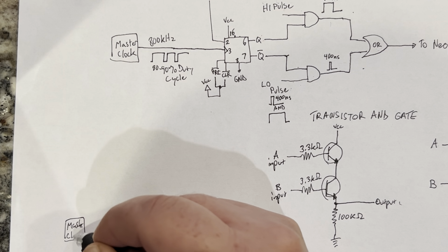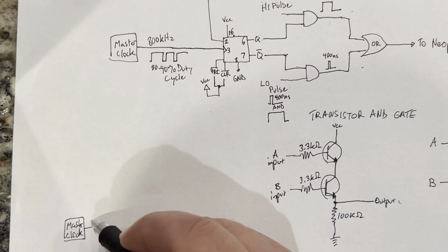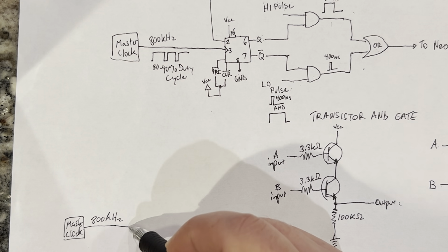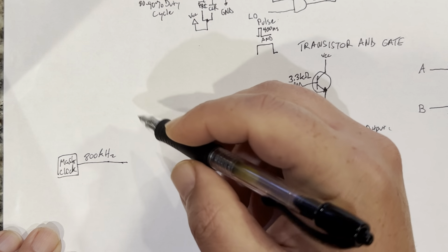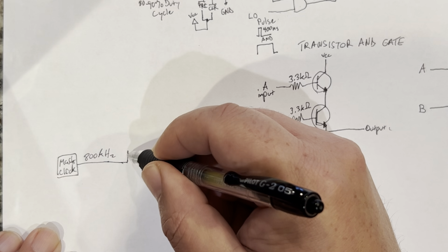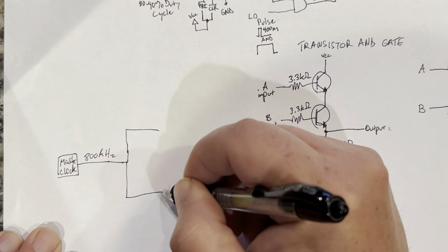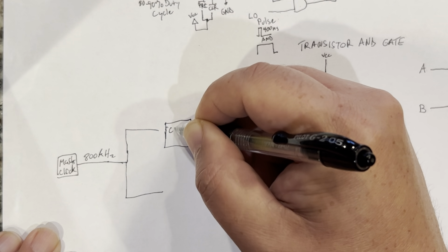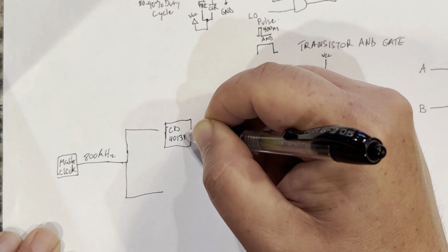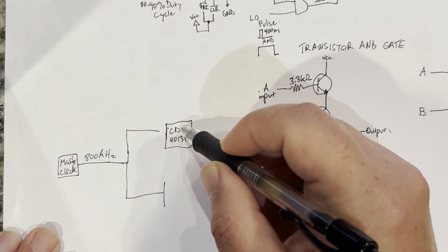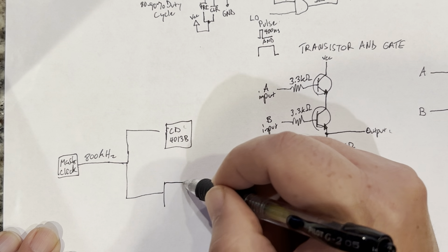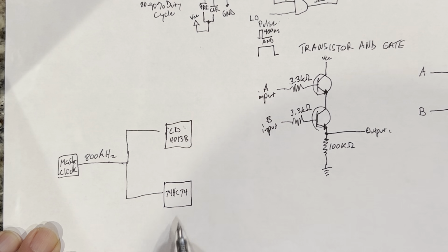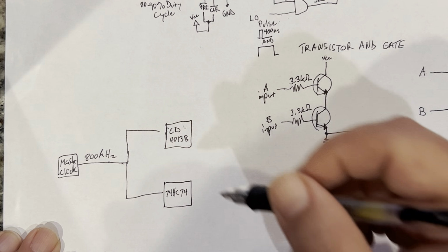master clock, 800 kilohertz, and I have it going to a CD4013B, which is the CMOS dual D flip-flop, and a 74HC74, which is the 7400 series D flip-flop.